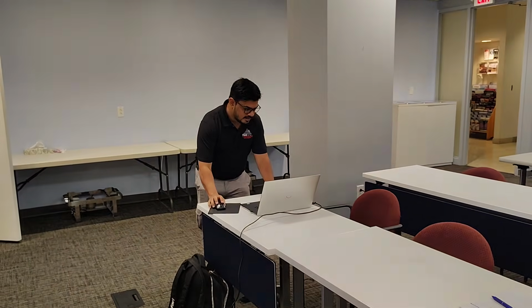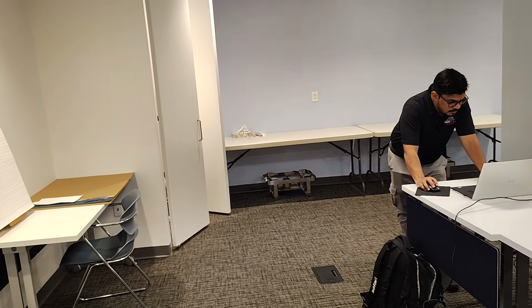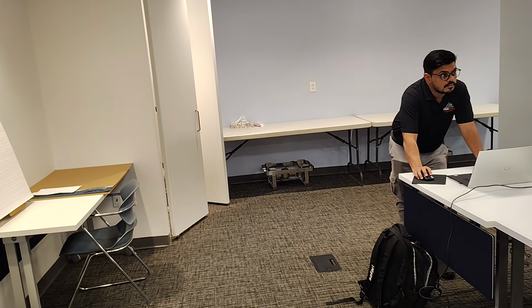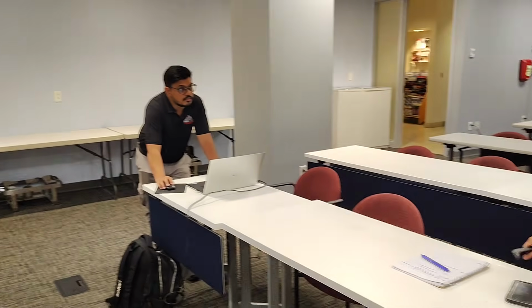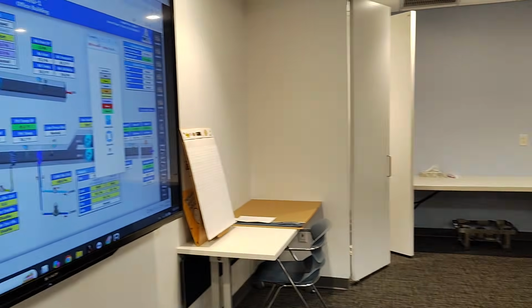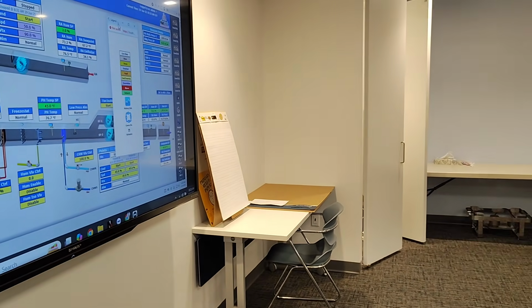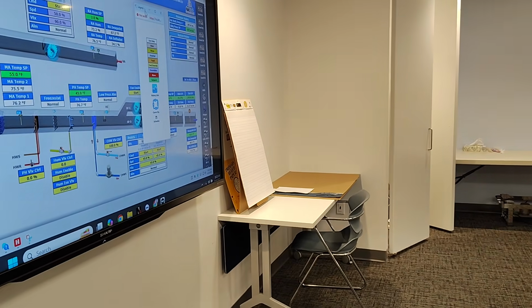Okay, let's continue. Now on this screen, I know it looks a lot different than what it did next door. Are we able to go and explain what every set point is? The green things are set points that you adjust. Only the green? Only the green. And the yellow? The yellow are outputs, or inputs that are functioning. That's the stuff that if you wanted to override, you could, but shouldn't. And then purple is overridden, correct? Yes, purple is overridden.